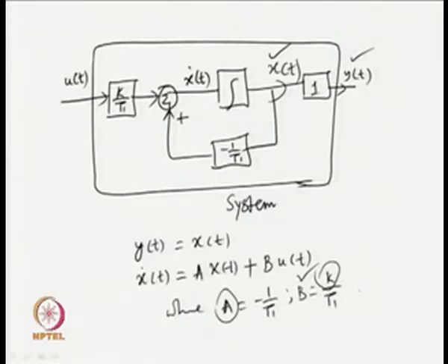So, these first order system dynamics can be given in this block diagram form. What is the beauty of this sort of representation in time domain? That one can include the initial condition in the systems. Where will the initial conditions come? This integrator.